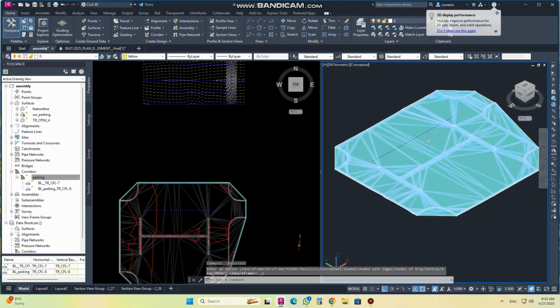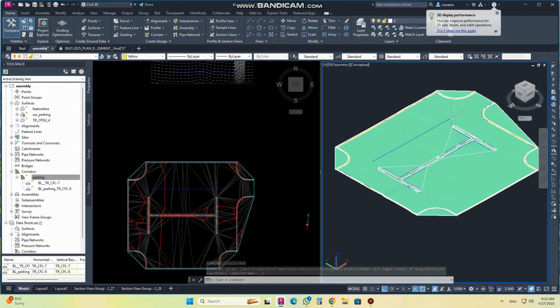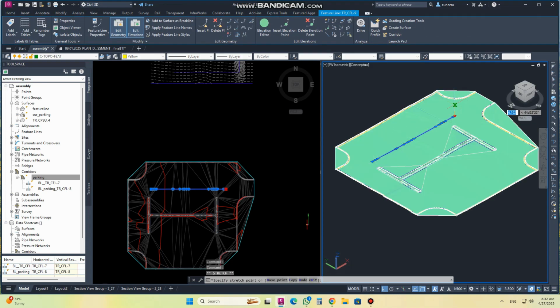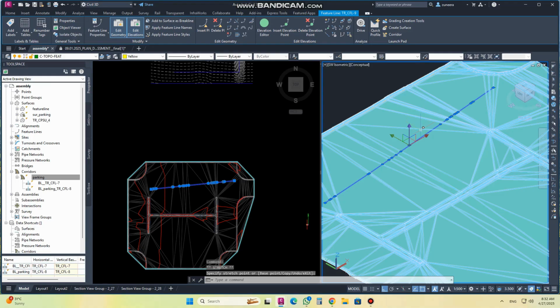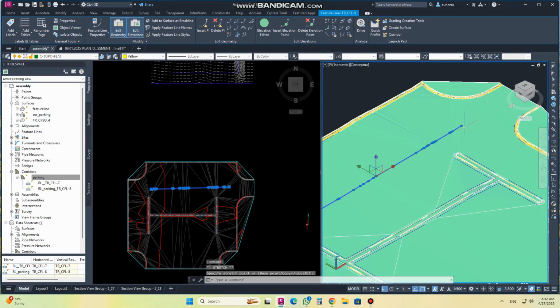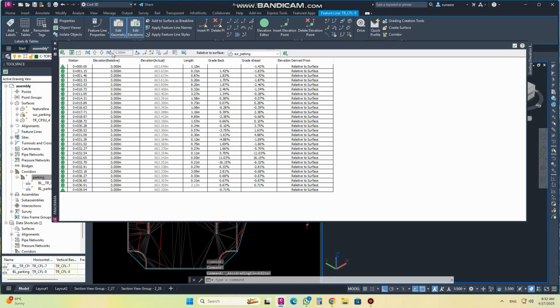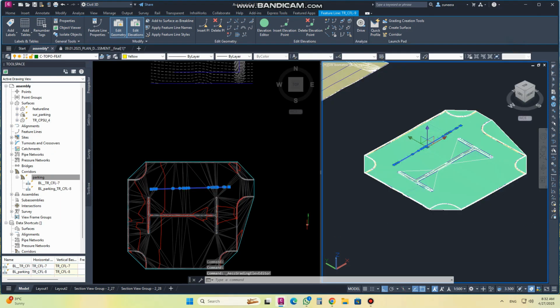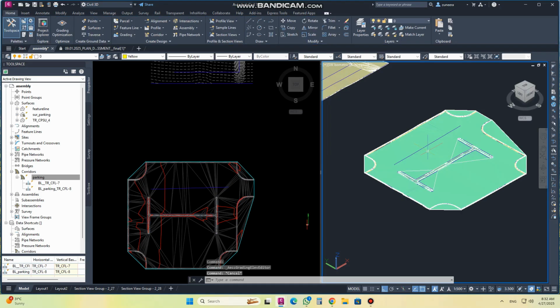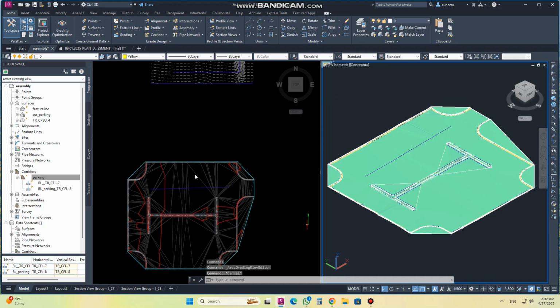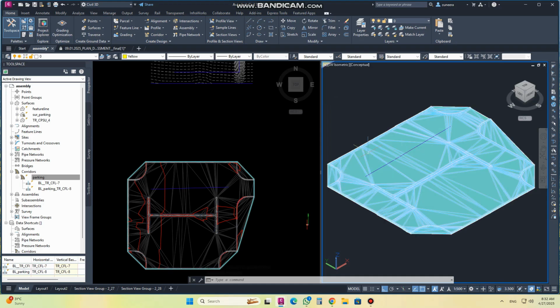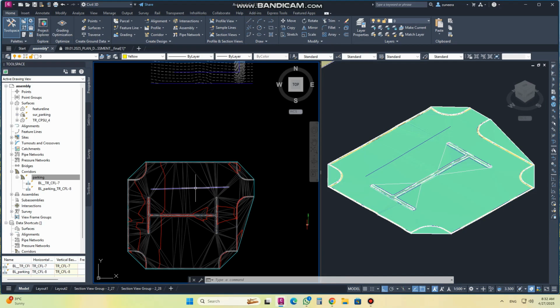As I move this line, if I move this feature line above, like if you give elevation to the surface, the surface will move with this one. So like this you can add any feature line to this surface, or take this line from the design, and forward you can add like this any feature line to your surface.